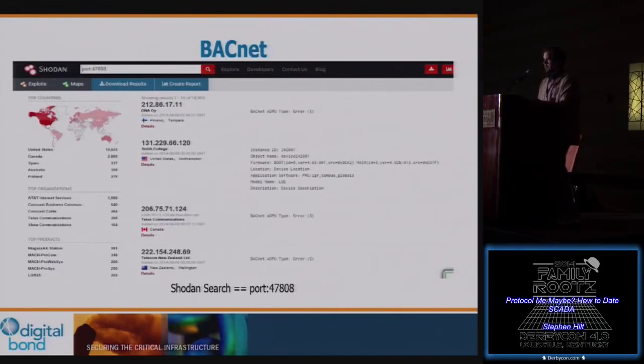We actually wrote, and I don't know if it actually made it in, a service probe for BACnet that I submitted to Nmap as well. So you can just run a quick version probe scan with -sV on that port, and if you didn't want to pull all the information but wanted to positively identify a device as BACnet, you could search those and query those further as they returned.